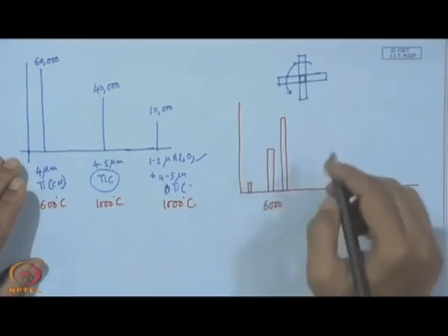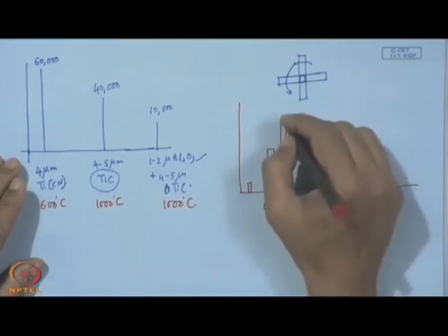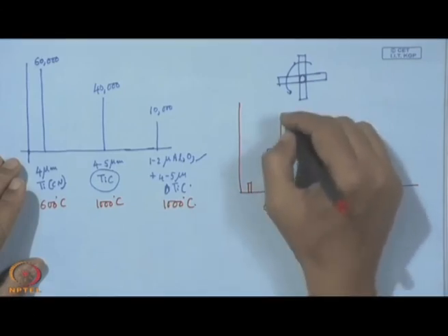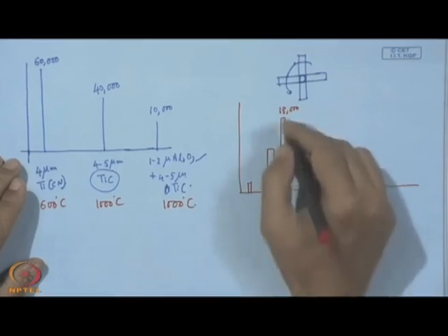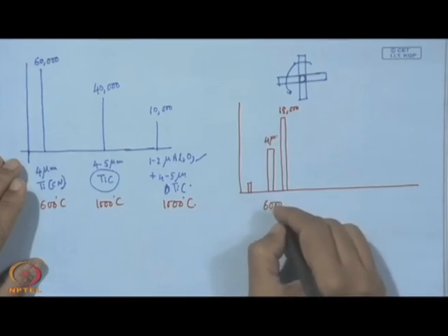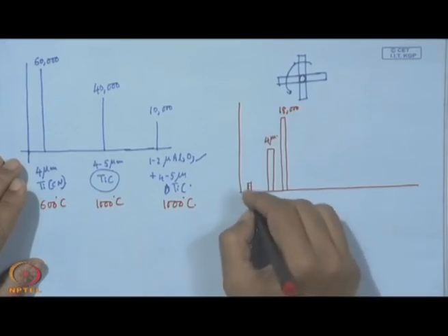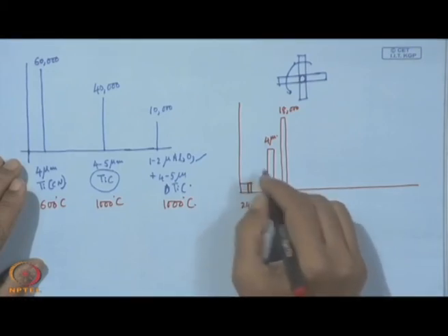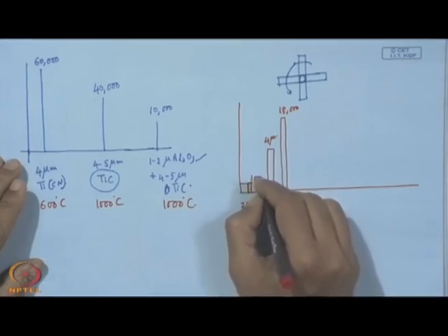We can also conduct this test, and here when it is 2 micron thickness, it can go to 18,000 impacts, but when it is 4 micron, it will receive only 6000 impacts, and when it is 24 micron thick, it can receive only 1000 impacts.